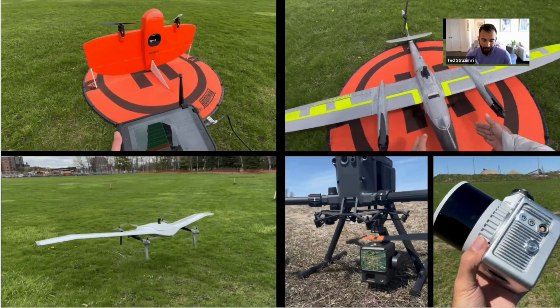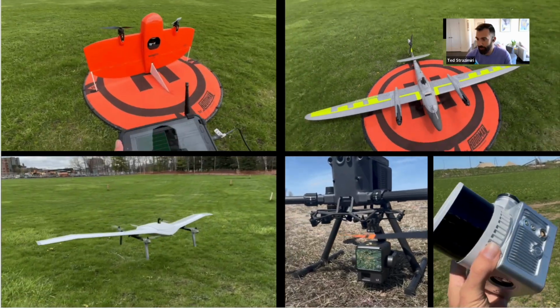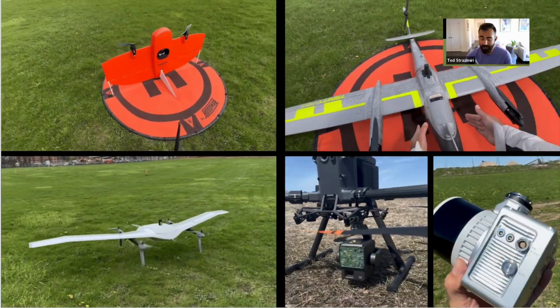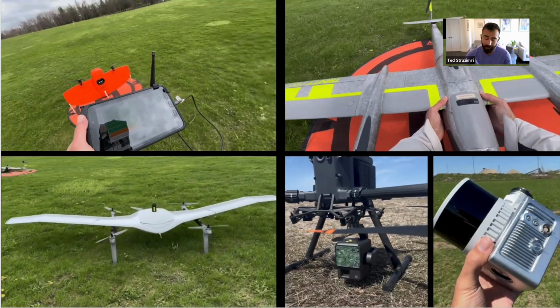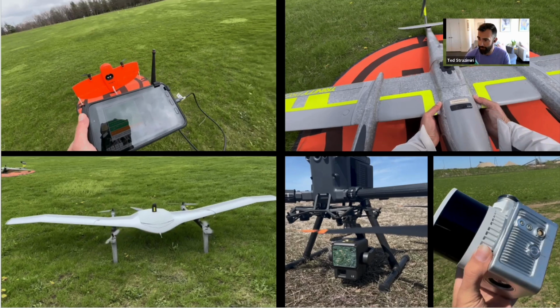And so, the thing about LiDAR is that it really doesn't depend on lighting at all. You could be flying at night. In fact, I think you probably see slightly better results at night, maybe some more, that probability of detection being higher. But with photogrammetry, you have to have good lighting conditions.